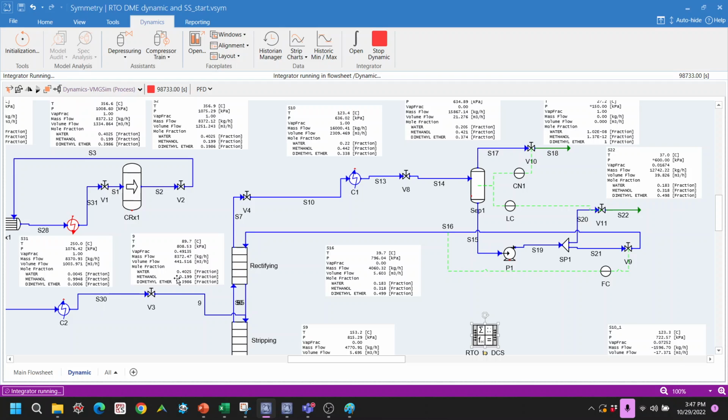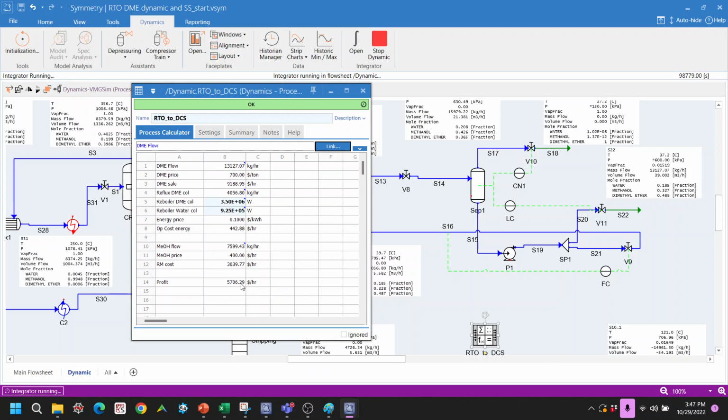Okay, in this case it's still circling. You can see that the DME specification is not being fulfilled because we are reducing the reflux. So the DME cannot be removed, it's 0.5% already. So we will have to wait. All of this goes to the slop tank, which is not really nice. So we'll run this, maybe leave it overnight and save the result somewhere. I also want to see if we can reach 271 something, because this is now still a very strange number.